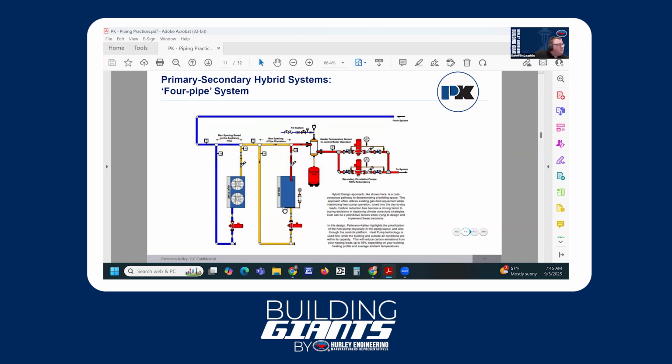The heat pump operates on its own loop and it discharges fluid into the returns of the condensing boiler. And we're going to prioritize its operation. It's always going to run first. It's going to be our lead appliance. And our lag appliance will be the condensing boiler in this scenario and only come on when we need the additional capacity. And this one, I believe, is going to become much more common. We're starting to see this already in our area. And this is an air to water heat pump too, by the way.